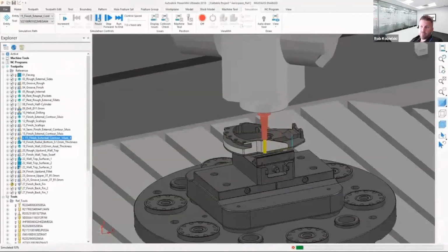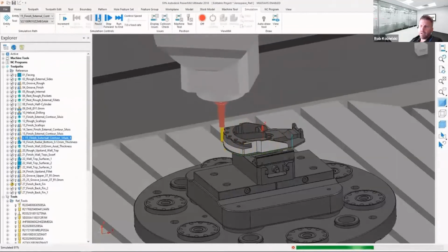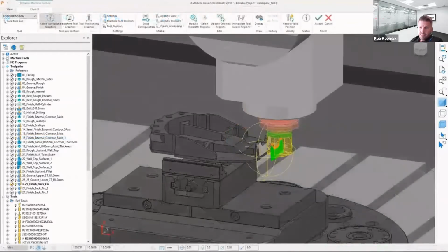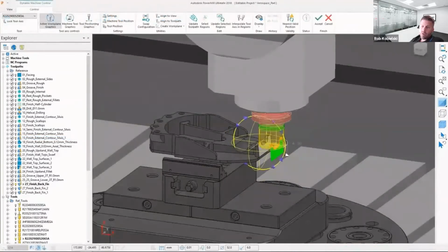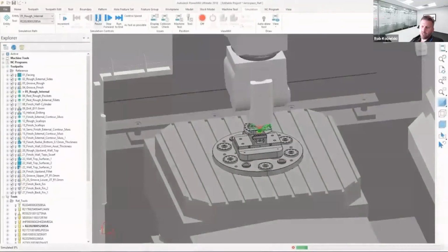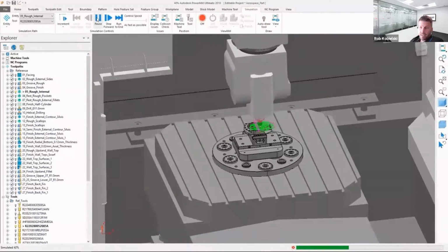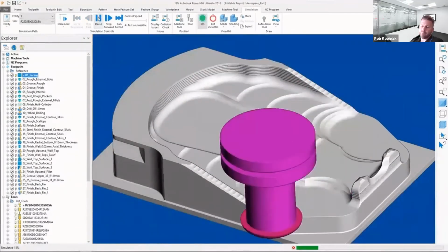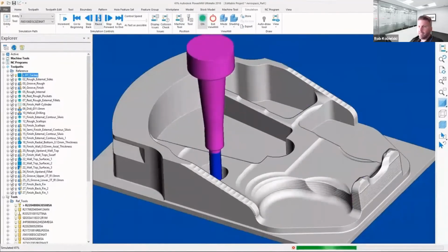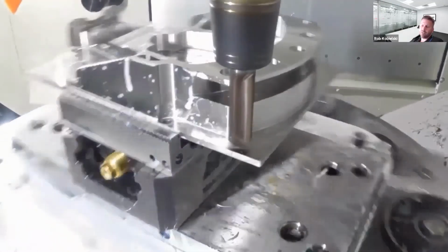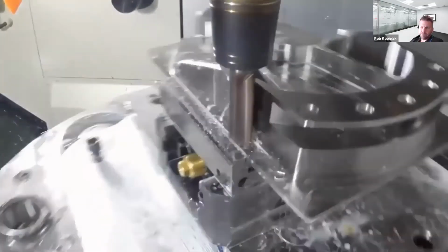Minimizing tool lengths to decrease vibration and improve surface finish can be achieved by utilizing the full capability of the multi-axis machines. Tool axis decisions can be made prior to calculation or quickly applied afterwards. This fine-tunes the output desired for that machine. Simulation and verification before live machining can reduce downtime, resulting in safe, optimized toolpaths critical for confidence for unattended production, as in lights out production. So Fusion 360 with PowerMill is the expert choice for CAM dedicated to producing exceptional quality and trusted to deliver.